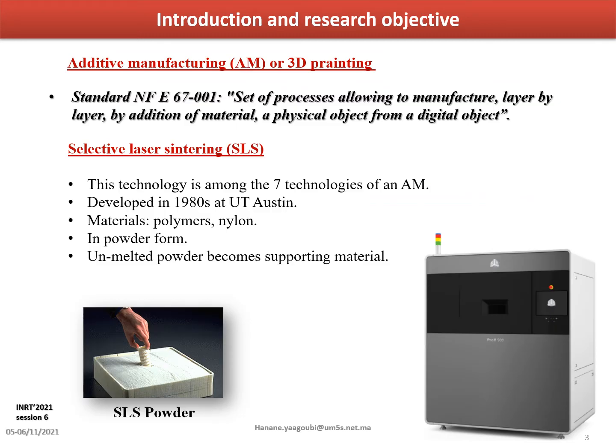First of all, the definition of additive manufacturing according to the AFNOR standard is a set of processes allowing to manufacture physical objects from digital objects, layer by layer, by addition of material. The selective laser sintering process is among the 7 technologies of additive manufacturing. It was developed in 1990 at the University of Texas in the USA, and the materials used are polymers and nylon. The materials are in powder form, and the unmelted powder becomes the supporting material.